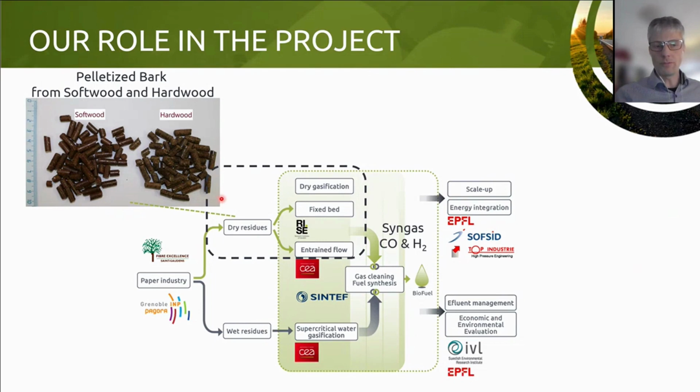Furthermore, we used two different gasification technologies within the Pulp&Fuel, both a fixed bed technology and an entrained flow technology. The fixed bed is generally good in the smaller scale, whereas the entrained flow concept is essentially the preferred option when it comes to larger scale installations. However, nevertheless, both technologies produce a product gas called synthesis gas, or syngas just in short.